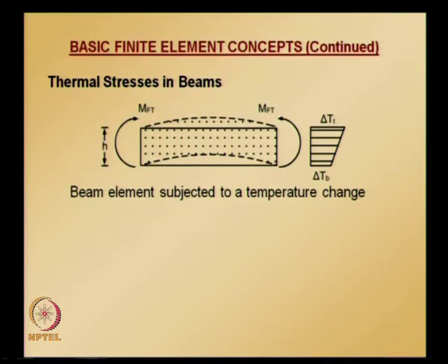And when a beam element like this is subjected to temperature change, it is going to experience curvature. Because of that, it is also going to be subjected to a uniform moment, which is going to be constant along its span.